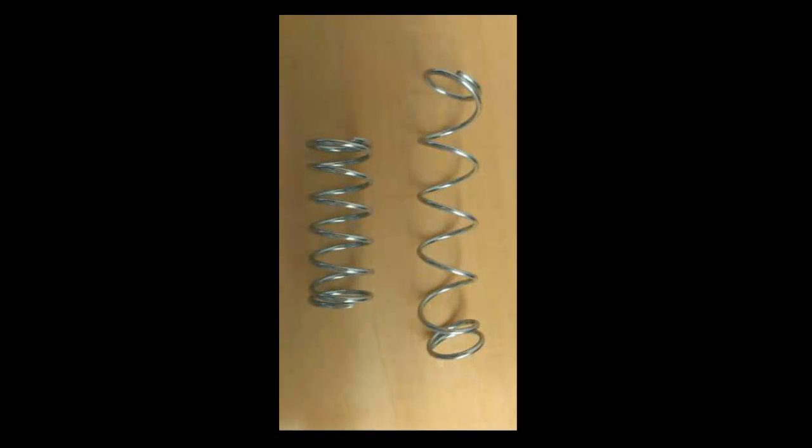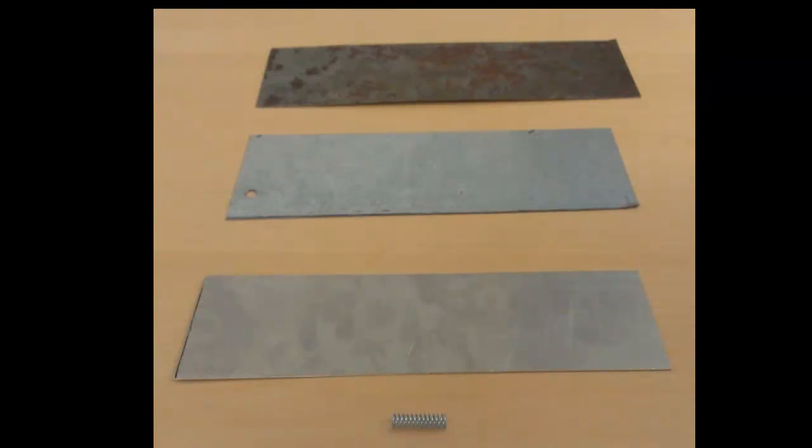Before we define elastic and plastic deformation, let's define stress and strain as they quantify deformation. Stress is a force applied over an area, or a pressure force. Strain is the change in length in the direction of load, a stretching or a compression. In this video, we will deform three materials by applying a bending moment through the material. However, deformation can be tensional, pulling the material axially, compressional, compressing the material axially, or torsional, applying an axial moment.